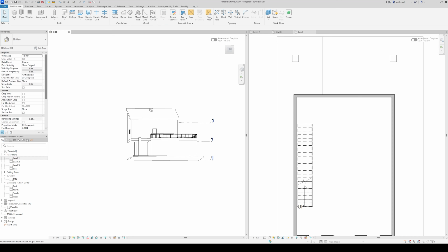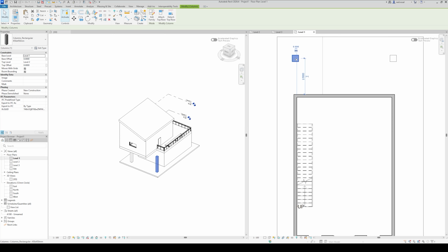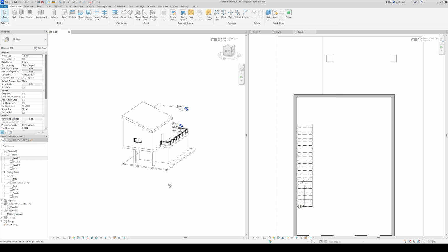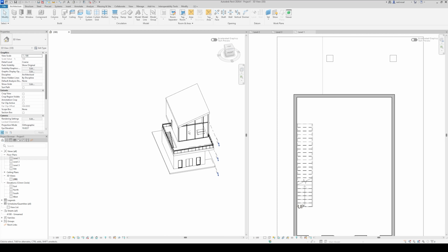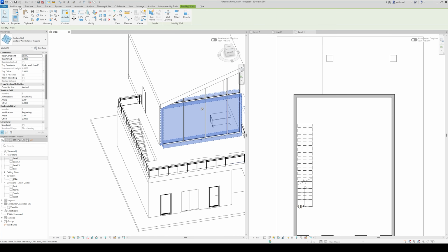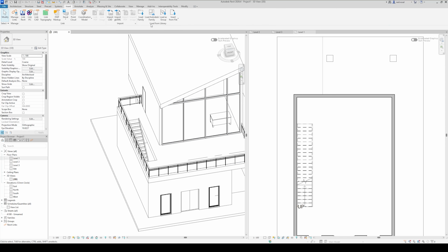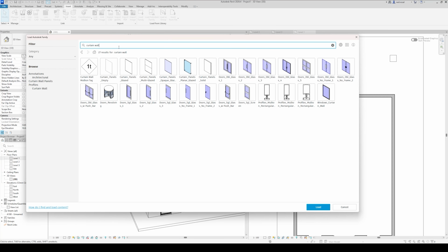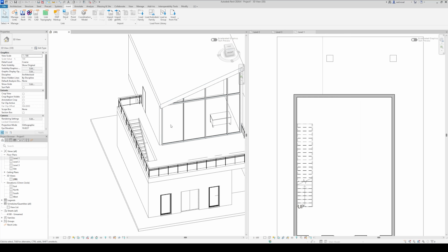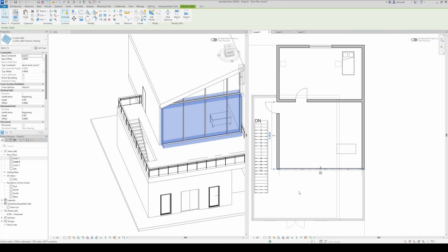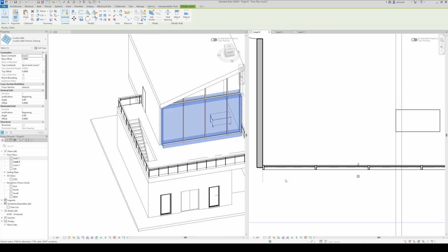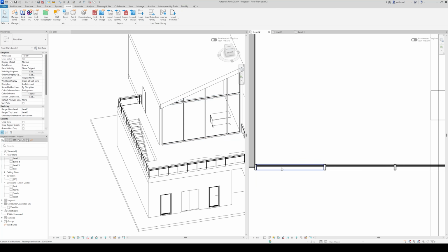As you can see, it's snapping. Oh boy. Yeah, that's plausible just for now. I also want to add a door here, so I need to go to my architecture. Oh, I gotta go to insert, because I don't have a curtain wall door. I already had searched that up. I'm just gonna select this. Go to level 2, and it's sort of hard to select some certain components of some certain fixtures in Revit.